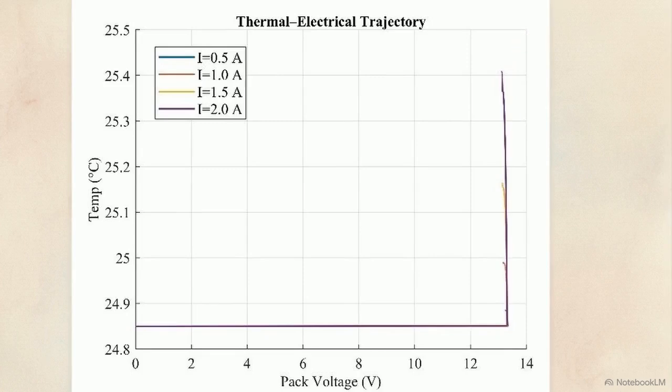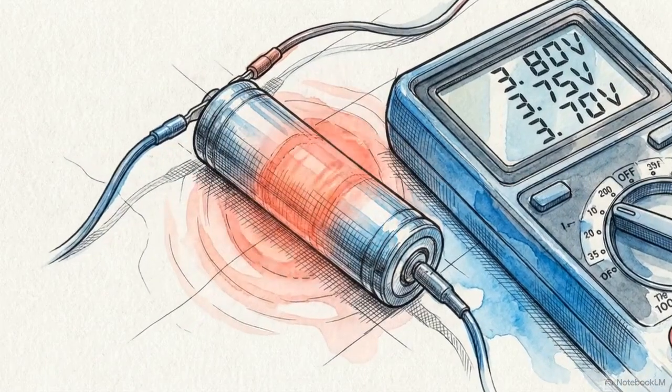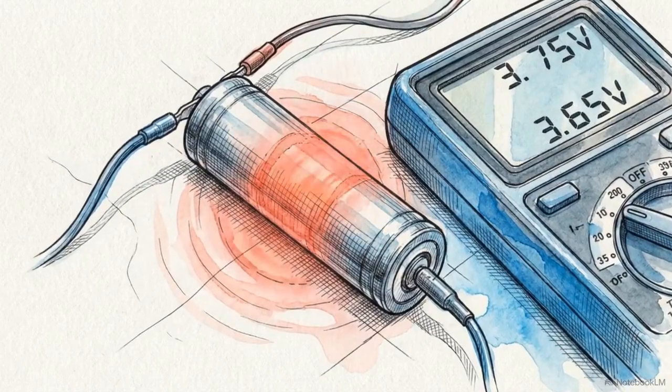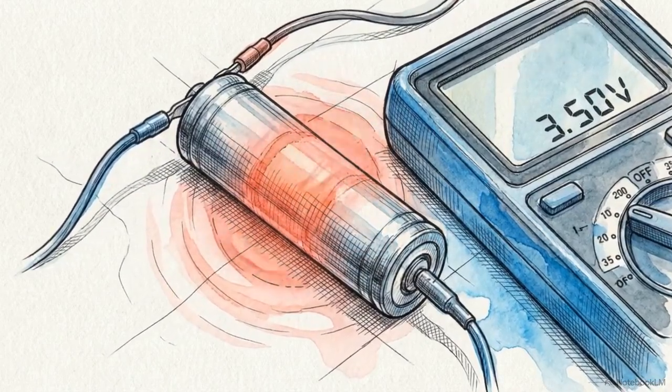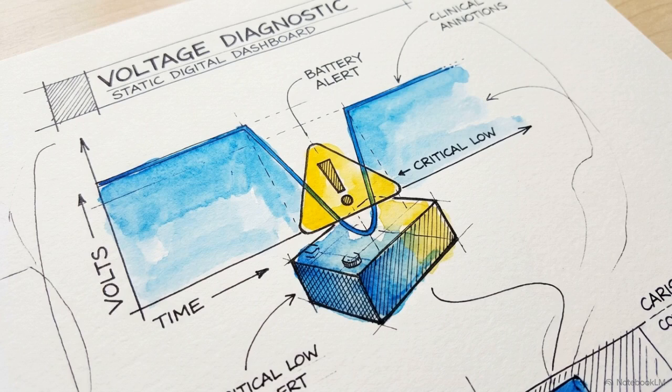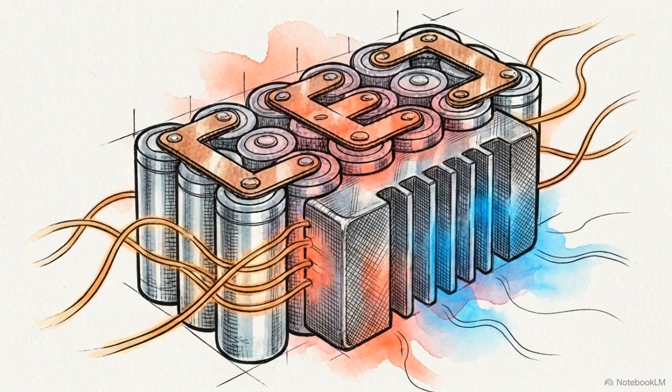A key observation here is that voltage deterioration manifests earlier and far more distinctly than the upward rise in thermal data. This makes voltage-based early warning indicators a highly effective tool for preventive control, allowing the BMS to respond to excessive load conditions before critical thermal thresholds are reached.